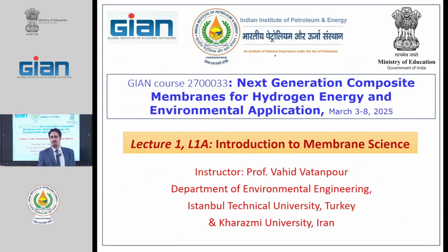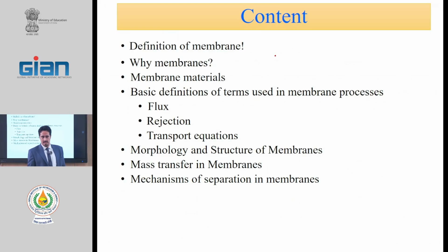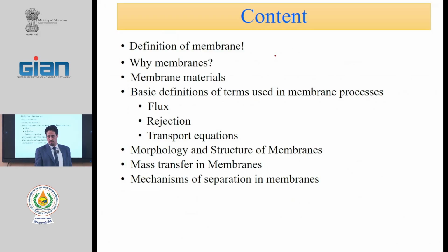In the first lecture, I will try to introduce the membrane and say what the membrane is and why we want to use the membrane instead of traditional methods, and what the mechanism of separation in membranes is. We will define the usual words used in membranes, such as rejection, flux, recovery, and others.